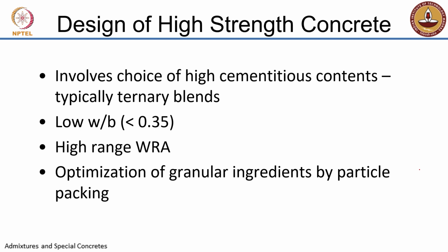When we do ordinary concrete mix design with only cement, we are not really utilizing the lower end of the particle sizes well enough. That's why when we start using fillers as replacement of aggregate, we are trying to fill up the smaller particle regions. And when we replace cement with finer mineral additives, that also helps to some extent in actually filling up the gaps in the smaller particle sizes.